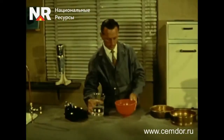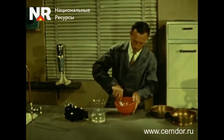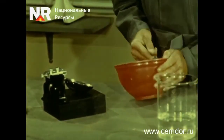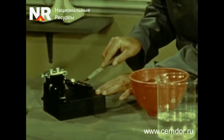The next important characteristic of soil is its plasticity. It is characterized by the plasticity number, which is the difference between the moisture content at the liquid limit and the moisture content at the plastic limit. For this, the soil is crushed and mixed with water to prepare a paste-like mixture.